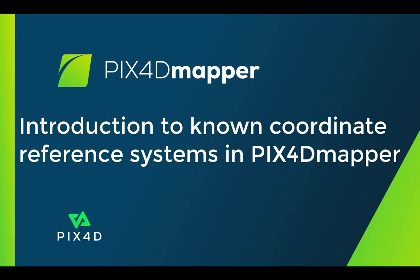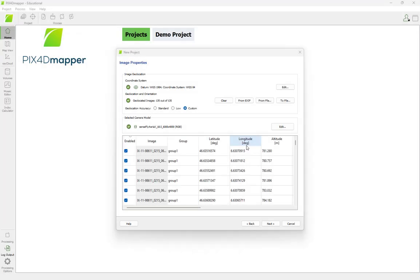In this video, we will discuss how to work with a known coordinate reference system in Pix4Dmapper. In Pix4Dmapper, the image coordinate reference system is set during the project creation process. When uploading images, it is automatically identified based on the metadata associated with the images.